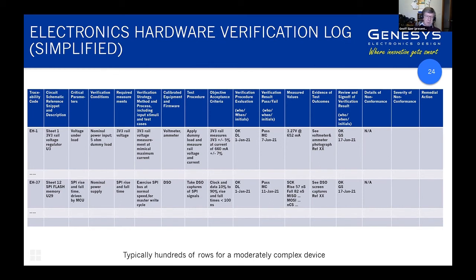For a voltage regulator, I'd probably have 8 or 10 other tests, looking at input and output regulation, ripple, transient performance, load transient performance, line transient performance, etc., doing cross screen caps and voltmeter and ammeter caps to show that the voltage regulator is doing what it's supposed to do.